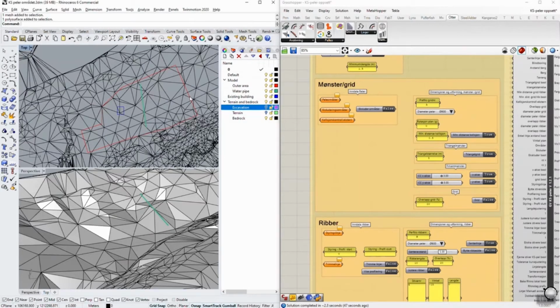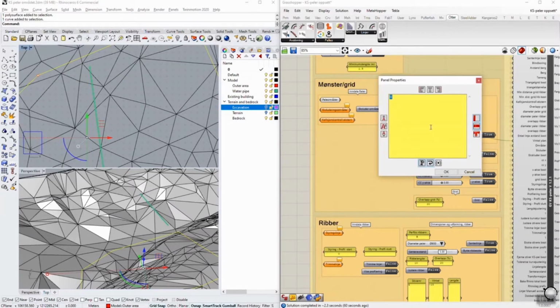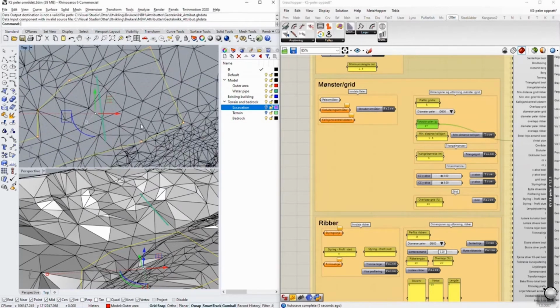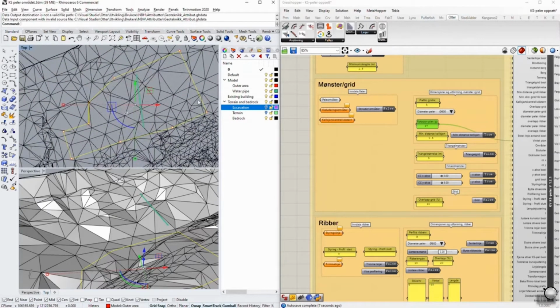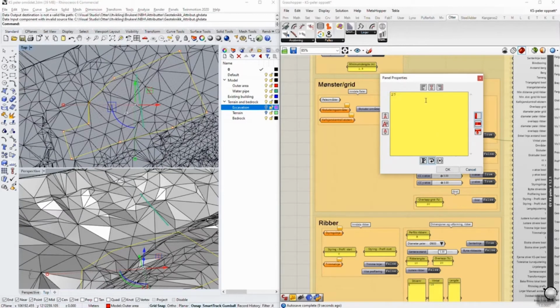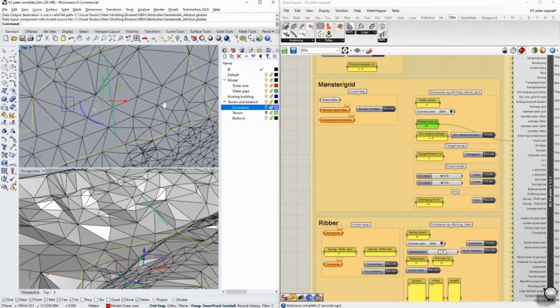And then making a grid of piles or columns, lime cement columns, choosing our outer area, and we'll define either a triangular or a square pattern, just to switch here in Grasshopper. So when done, we're just setting the right rotation, so the grid is roughly perpendicular to our outer boundary. So we'll just do a bit of adjusting on that. Let's have a look. Okay, make it 26 here instead, and then we're good to go.